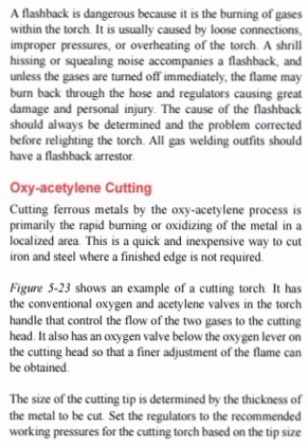Oxyacetylene cutting. Cutting ferrous metals by the oxyacetylene process is primarily the rapid burning or oxidizing of the metal in a localized area. This is a quick and inexpensive way to cut iron and steel where a finished edge is not required. Figure 523 shows an example of a cutting torch.